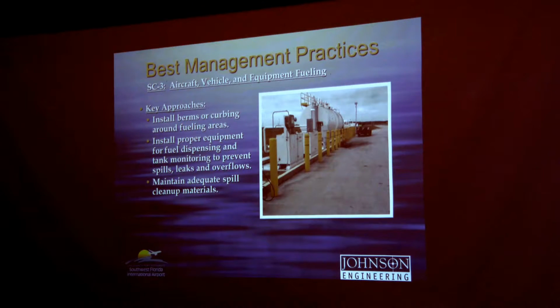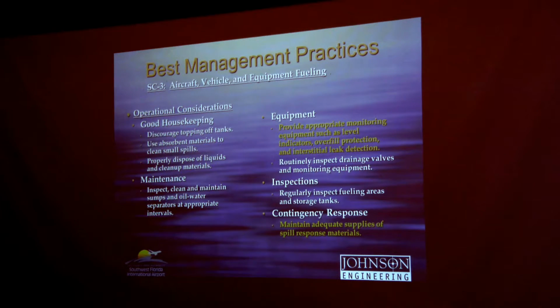SC3, aircraft, vehicle, and equipment fueling. Key approaches here, installing berms or curbing around the area to keep the fuel where it's supposed to be, installing proper equipment for fuel dispensing and tank monitoring to prevent spills or overflows, and maintaining adequate spill cleanup materials at all sites. Additional considerations include discouraging the topping off of tanks, using absorbent materials to clean up small spills, properly dispose of liquids and cleanup materials, inspect, clean, and maintain the sumps and oil water separators, routinely inspect drainage valves and monitoring equipment, and regularly inspect fuel areas and storage tanks.